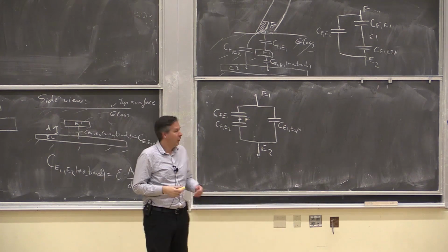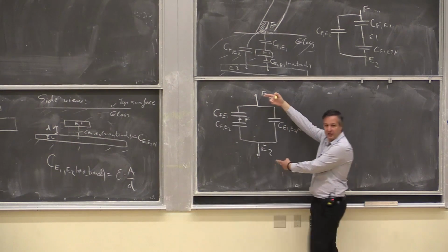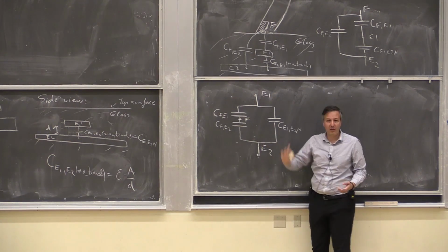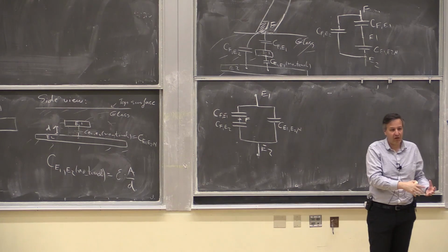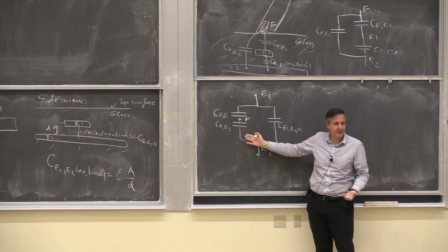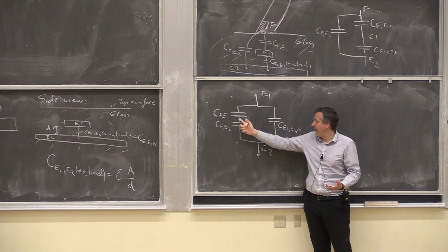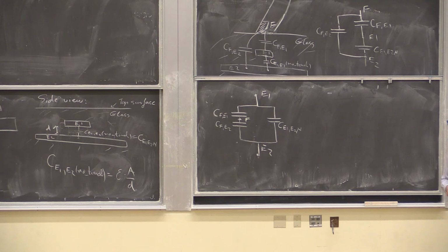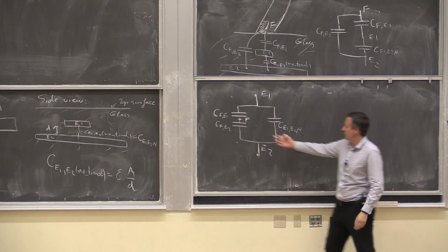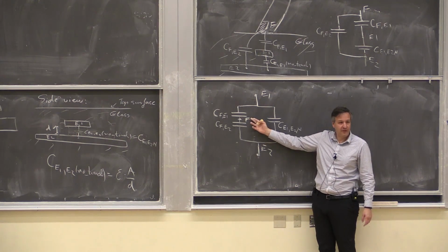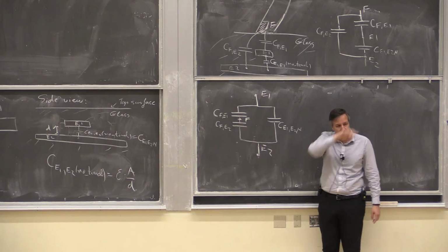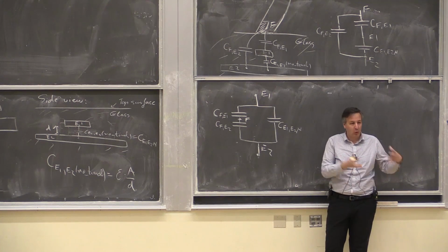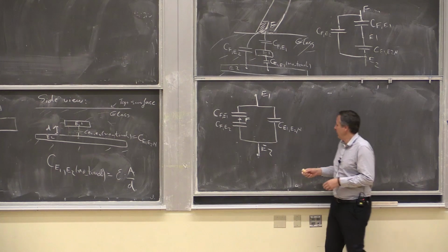Okay. So you see, from the standpoint of the circuit that's going to do some measurement here, I don't care. I just care that the finger is there because it creates these two new capacitors. But I don't really care about what's the potential on that node necessarily, right? So that's why all this stuff that we talked about, whether the finger is grounded or not, zero potential, that doesn't matter at all, right? I don't care what's the potential of the finger. I just care that it introduced these two capacitors that I can measure, because I'm going to be measuring total capacitance, right?